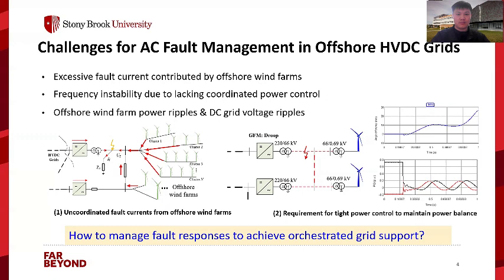Under such conditions, offshore AC power grids will be power electronic device-dominated systems. Handling faults in such grids will be more challenging. Uncoordinated control during faults can increase the risk of triggering larger grid disturbance or even blackouts. First, all wind turbines and HVDC inverters inject massive reactive power to boost voltage, as shown in Figure 1.